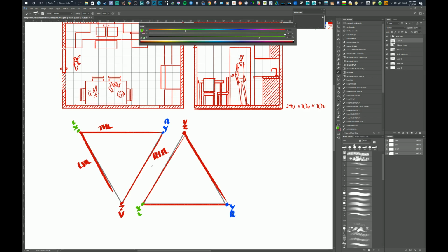The reference lines are the only lines in the perspective system that can receive units foreshortened from a measure bar using a measure point. Now, I might have multiple measure bars in a scene, which means that for each vanishing point I'll have a reference line per measure bar. But we can get into that later.